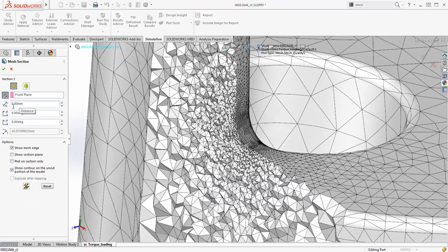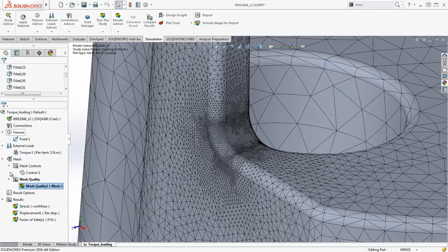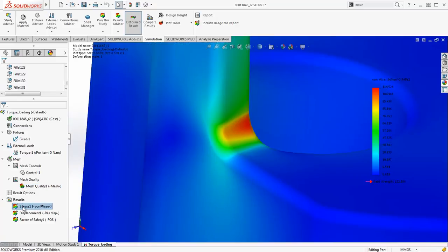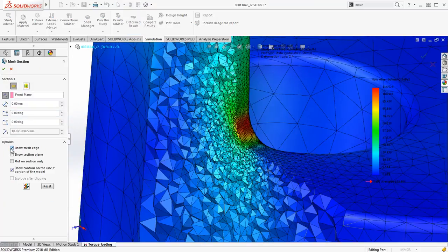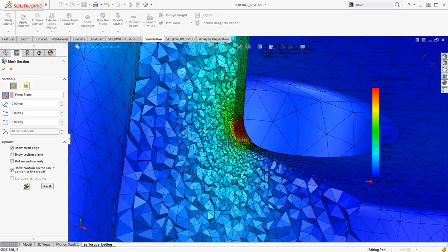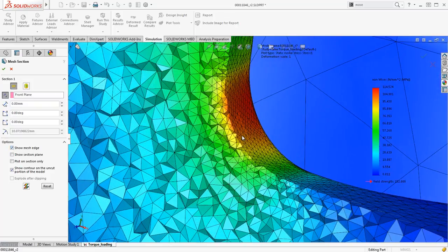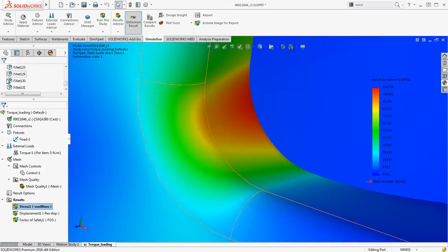The mesh cross-section can also be viewed on result plots using two methods to provide additional insight. Using the mesh sectioning capability highlights the elements that intersect the selected plane with the added benefit of now seeing the results variation across the elements. This can be adjusted to show only the intersecting elements or interactively drag through the model.